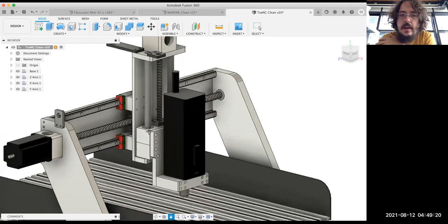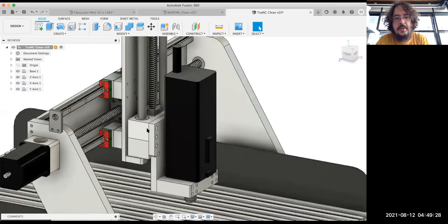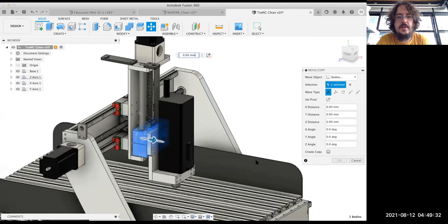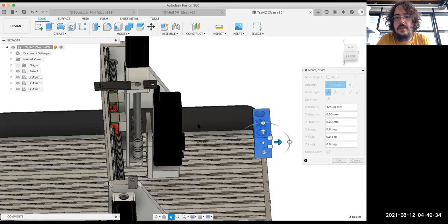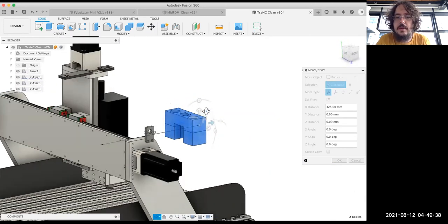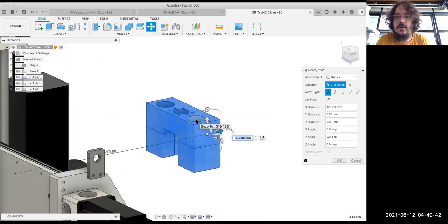And guys, this made this system very complex to realize because these shafts need a plate on the top, they need a plate on the bottom, they need these big pieces that we have been manufacturing ourselves to hold the bearings. And to fit the bearings inside, I killed all my bench vices because they were made out of cast iron, and to push the bearing inside, they all failed and broke. So now I have only forged steel bench vices just to do this, just to tell you.